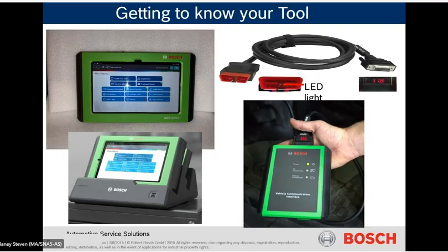And then something that's really awesome is at the end of the cable where it plugs into the VCI, there is a voltage reading. So it does read battery voltage. And it serves a couple things. One thing is that you would know if the vehicle, of course, is powered, if your VCI is powered, but you would also know if the battery voltage is dropping too low for you to be able to accurately scan. It will start flashing low voltage, and it knows at what point that vehicle's voltage gets too low for you to be able to scan accurately.